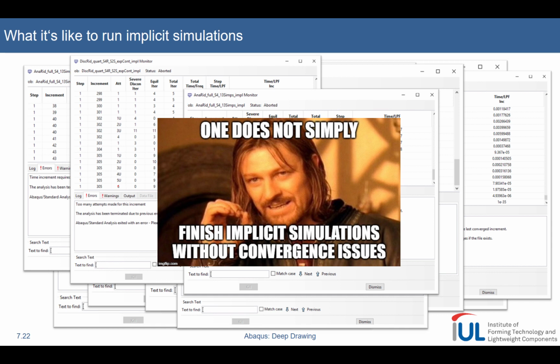Accurate physics, they always calculate equilibrium conditions in every state. So usually they are used to be compared to analytical formulas or experimental data, or even to verify or validate explicit simulations, because in explicit simulation, you don't have a real equilibrium all the time, so you should analyze the results with care if you look at explicit simulations.